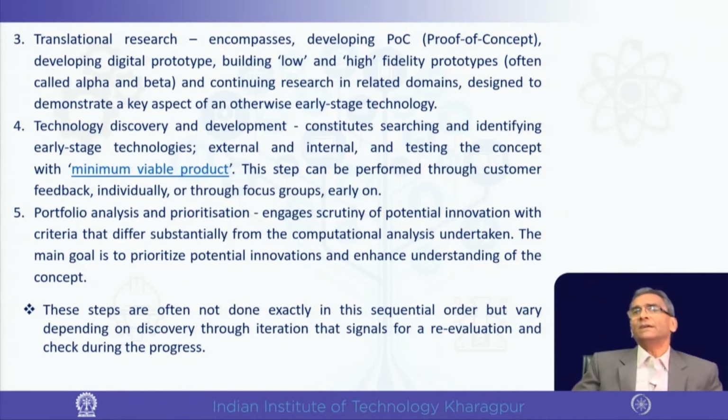Say for example, if someone is trying to check a gear, whether the mechanism is functioning, one can use a 3D printed material of plastic or maybe wooden ones to check whether the mechanism works. But in actual practice, to withstand the real load, maybe then full scale alloy steel material is to be used, which is the beta prototyping.